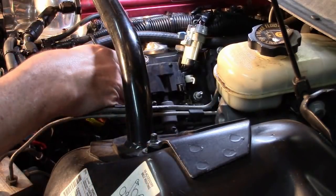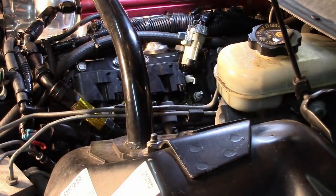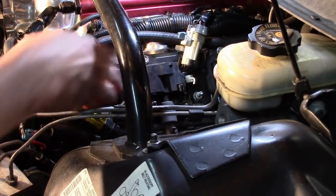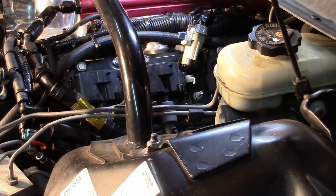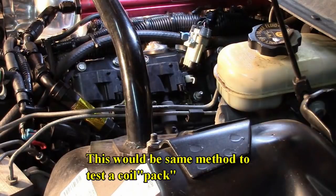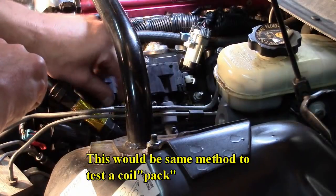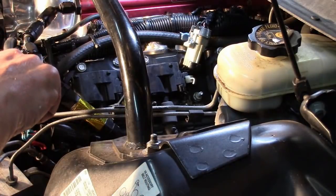All right, now looking at this design, each coil has a connector under it, and each connector has 4 wires. One of the problems here is that being able to back probe these like on that last video so that we can show some of the testing is going to be very difficult on this. So actually, we're going to step things up, and I am going to use this common connector for everything, because I really don't feel like pulling the coil out, because even if I did, I just don't think there's enough clearance here that I can back probe it.